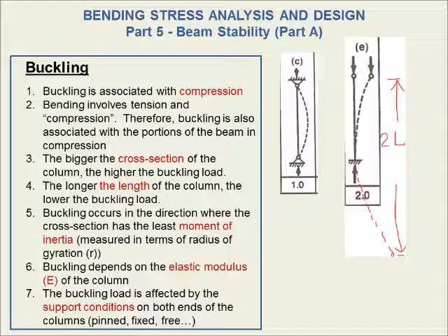Okay, so as I said, this is not very intuitive, but if we do experiments, we can find out. We can pin this ruler, hold it free to rotate, and then try to buckle it. We can put it in a vise and try to buckle it. We can leave one end free and then push it down and try to buckle it that way. And we will see that the shape of the buckling varies, all right? And the way in which we conceptually capture this is by using the effective length, which I have just described, right?